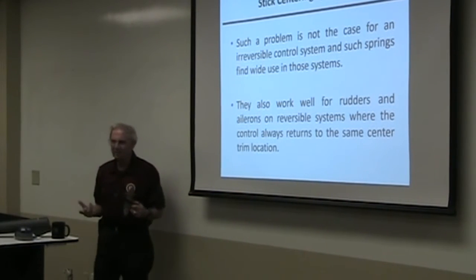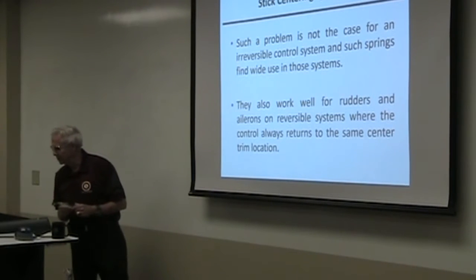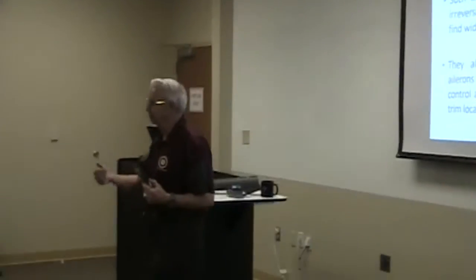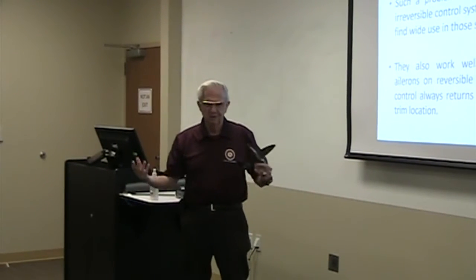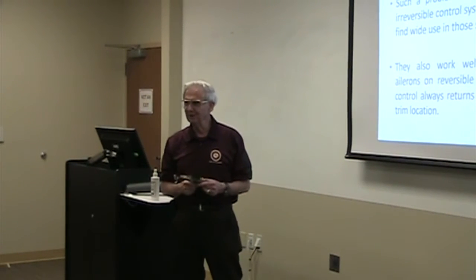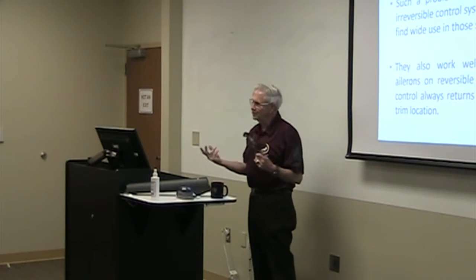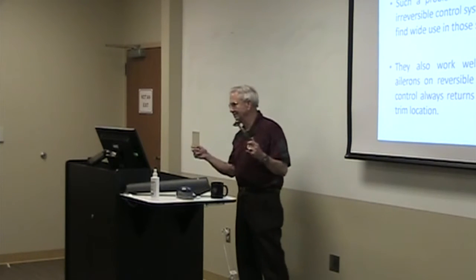However, that's not a problem for an irreversible control system, because the stick can always come back to the same position, because you're not connected directly to the control, or not mechanically anyway. So the stick can always come back, and as a result, you find centering springs used in irreversible systems quite often. That's one way to get the force, and you can increase the force and decrease the force by stretching the spring.